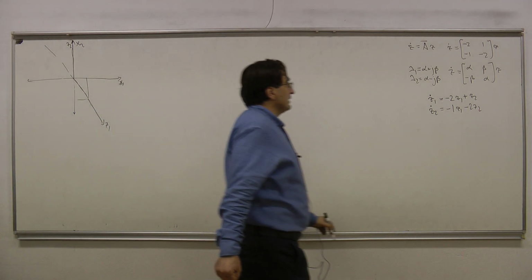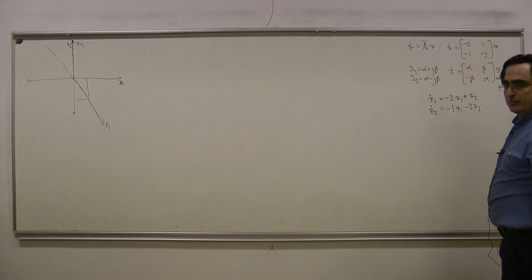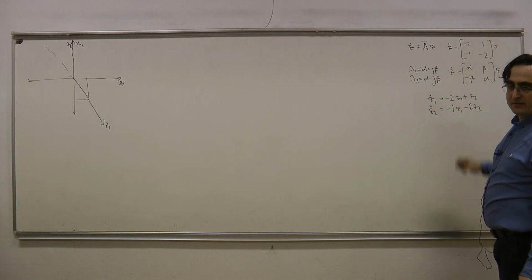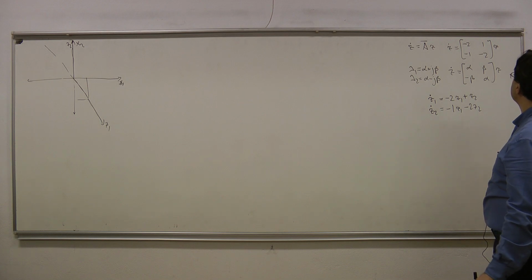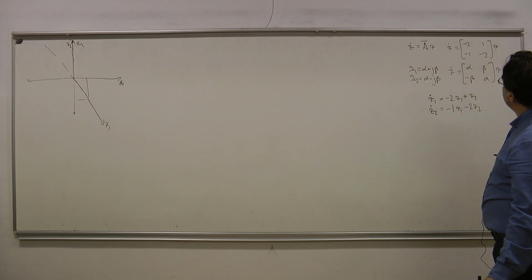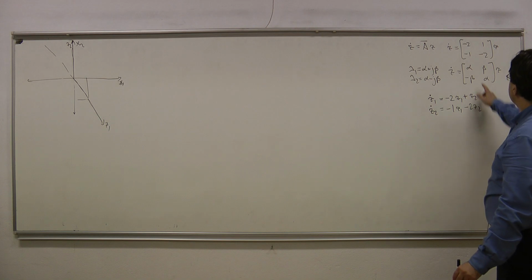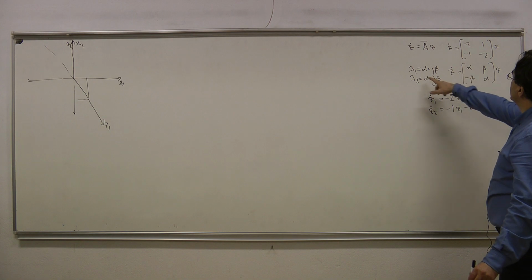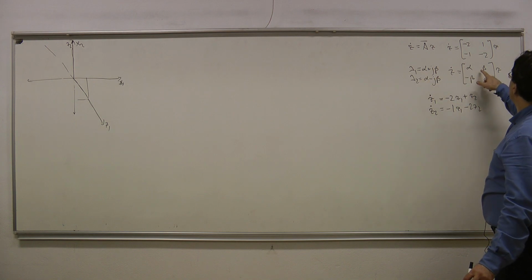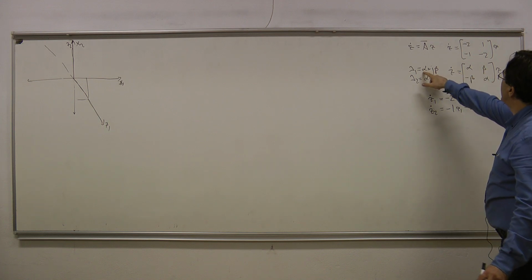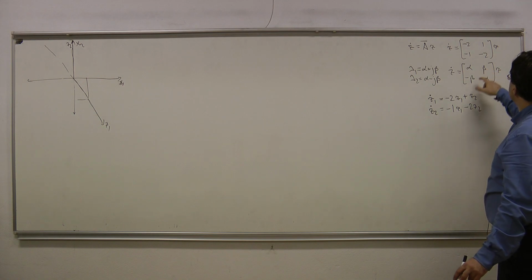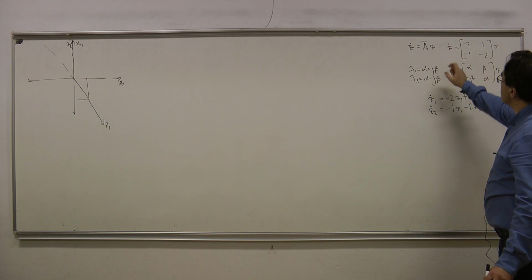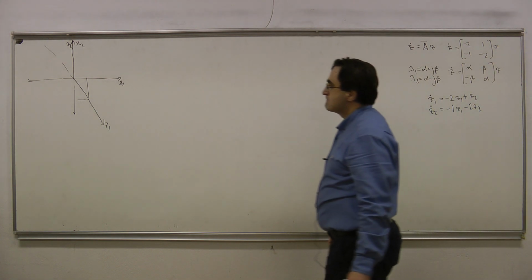And we have shown that in this new coordinate system, our complex system, x dot is equal to ax, looks a little bit simpler than the original one. Okay? On the real elements of A bar, I have the real part of the eigenvalues, and in the off-diagonal elements, I have the imaginary parts. Okay?